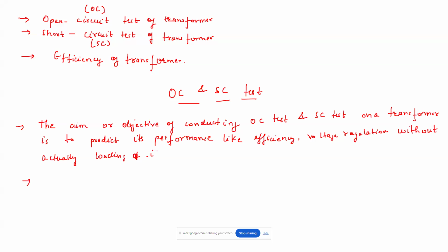Once you have the equivalent circuit parameters, you can basically study everything. You can study the efficiency, the voltage regulation and other performance characteristics of the transformer.